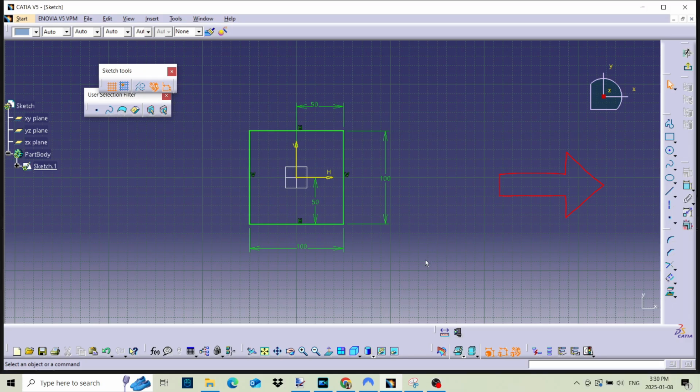If we look at the toolbar on the left of the screen, we can see there are many more icons to choose to create the profile. The profile that we just used is a free drawing tool that you can use to create any shape you require. The other icons in the menu will produce a single type of profile, for example a square or a circle or an ellipse. Let's have a look at using the square command. Pick the small triangle to expose the extra menu, select the square icon,